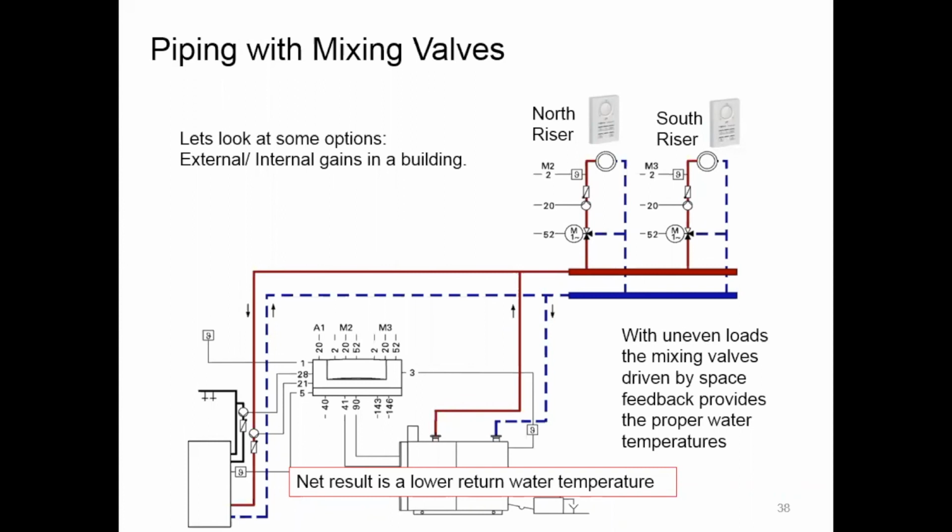of the boiler. So when we start to look at boiler efficiency and we start to look at driving it, we typically take a hard look at mixing valves as part of the package to help drive the overall efficiency. And again, we can make some fairly dramatic gains by adding a mixing valve into the package.